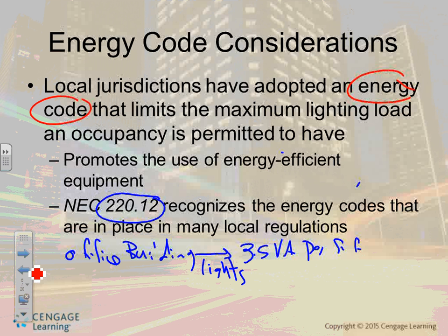And number three, you are to provide efficient equipment in your building. So, look at this fixture. I will provide an efficient ballast for this fluorescent fixture or LED driver for the LED fixture, the most efficient one. That's requirement one. Number two, I can provide a volt amp that meets the NEC code book.